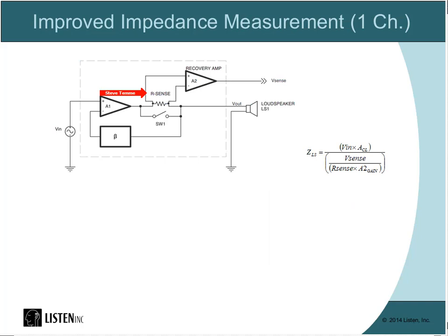And it has several benefits. So we still get a voltage, in fact, a voltage with a particular sensitivity to the current due to the sense resistor. Just like we did before, the voltage out is actually the signal going into the amplifier times the gain. But the current is all calculated inside the feedback loop of the amplifier.